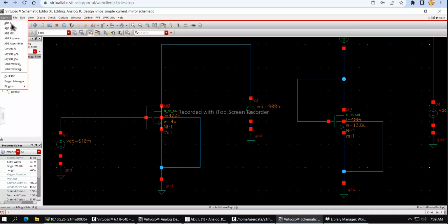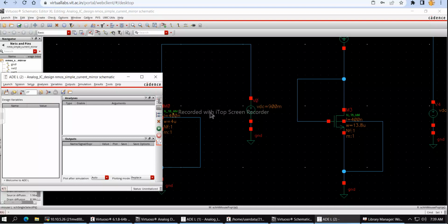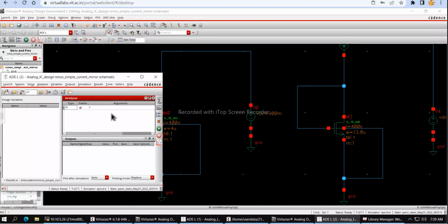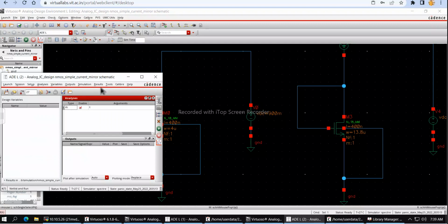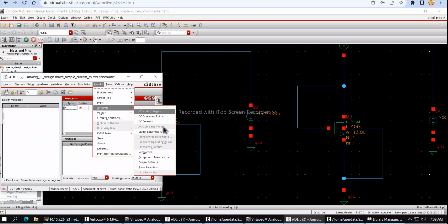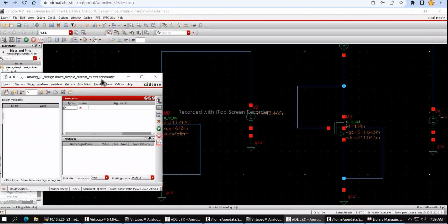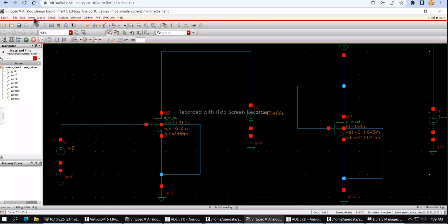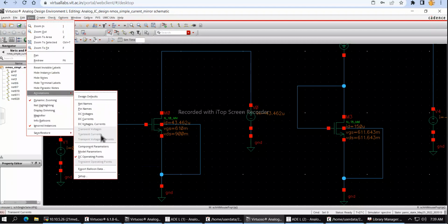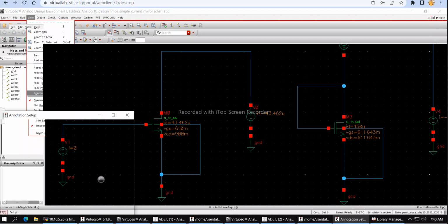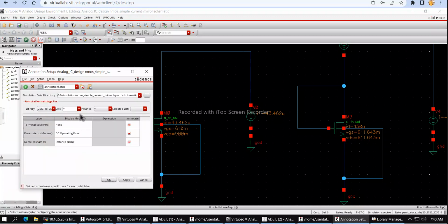In simulation, the threshold voltage value varies depending on many parameters. So we shall do the DC analysis. We shall save the DC operating point and annotate the DC operating points. From this we need to obtain the value of VTH, and we also need the region. Go to setup, then we need to annotate the NMOS.